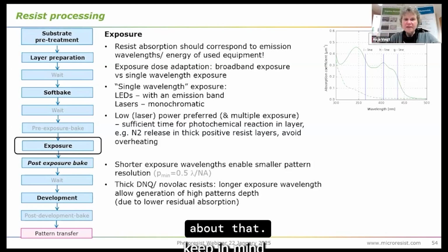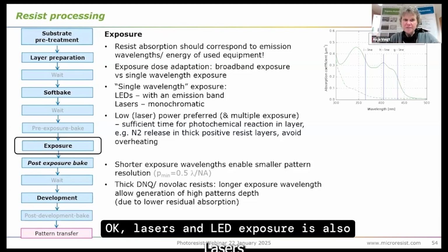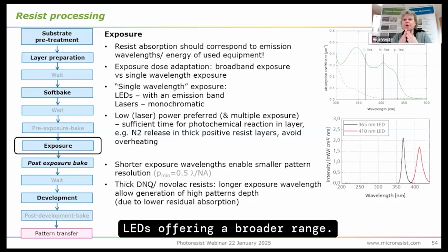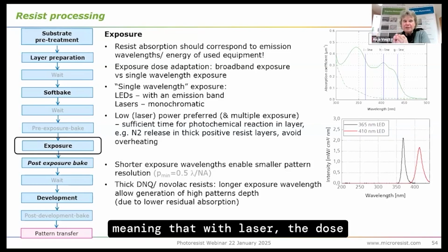Then, okay, lasers and LED exposure is also possible. LEDs offer a broader range, while laser direct writing has clearly monochromatic light, meaning that with laser, the dose is slightly higher than for LED because of the broader emission band.